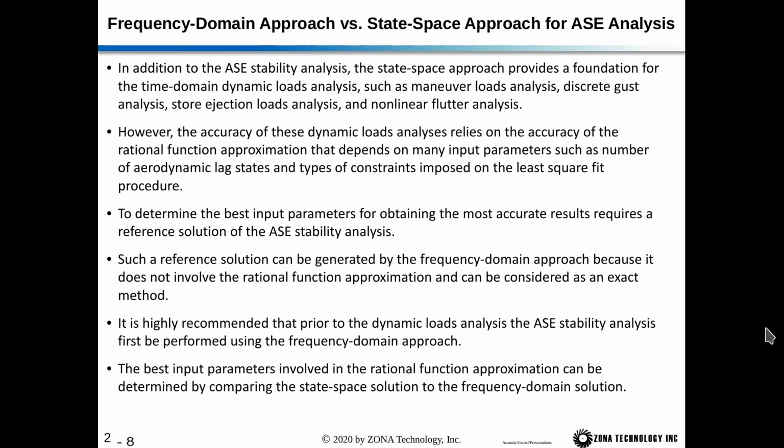So now let's compare the frequency domain approach and the state space approach for the ASC analysis. Now, in addition to the ASC stability analysis, the state space approach provides a foundation for the time domain dynamic loads analysis, such as maneuver loads analysis, discrete gust analysis, store ejection loads analysis, and the nonlinear flutter analysis. However, the accuracy of these dynamic loads analyses relies on the accuracy of the rational function approximation, and that depends on many input parameters, such as the number of aerodynamic lag states, those aerodynamic lag state values, and the types of constraints imposed on the least square fit procedure.